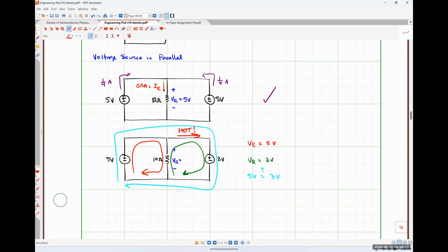And so we had to tell the students after leaving class every single time, hey, make sure you take the batteries out of your battery pack, because we would just have them connect the wires directly to the breadboard to power things up. If you accidentally cross those wires, the battery pack would heat up enough that it would melt your little bag that your kit came in. Very, very dangerous. So that's why we stopped doing that a couple of years back.